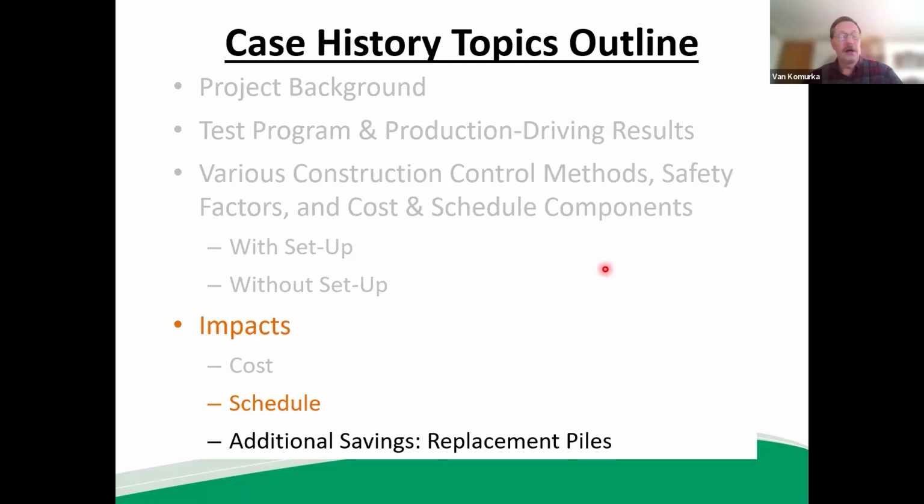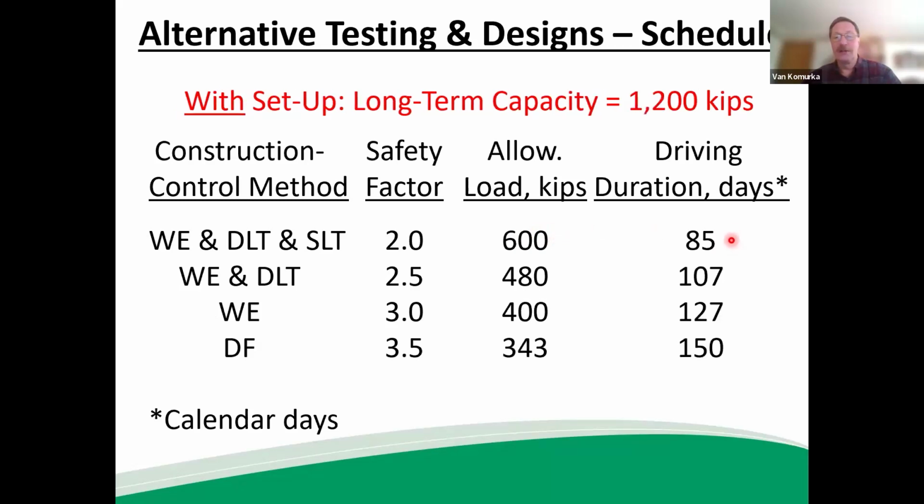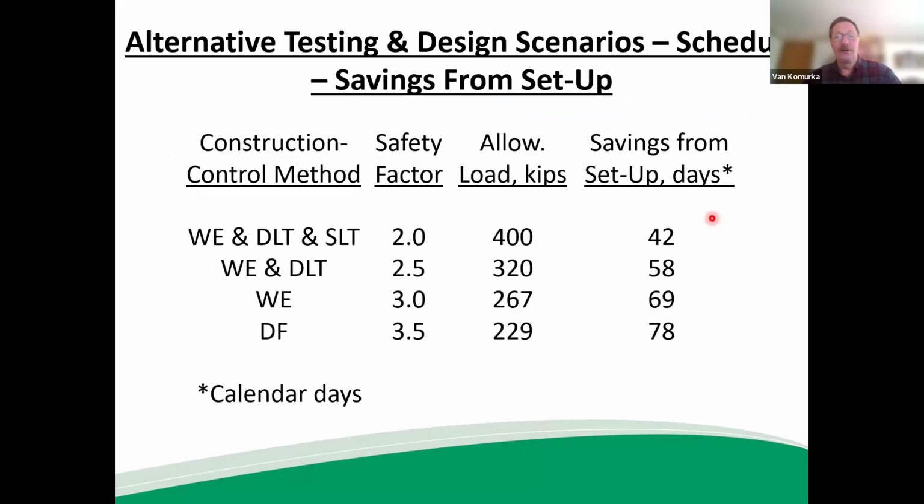We talked about cost and schedule and risk as the 3 things that come out of a test program. So if we had designed and installed the piles without setup, and we started with an ultimate capacity of 800 kips, we would have had an allowable load of 400 kips and a driving duration of 127 days. Incorporating setup, the driving duration drops to 85 days. And so incorporating setup actually saves 42 days of driving schedule.